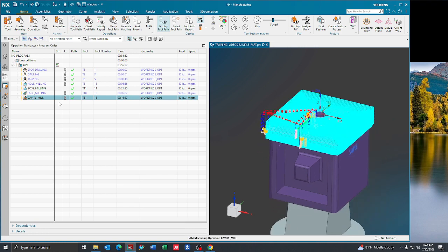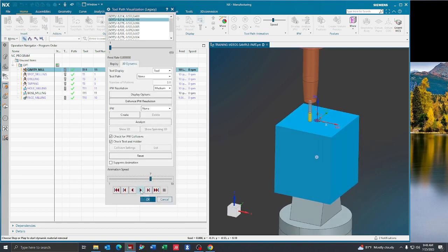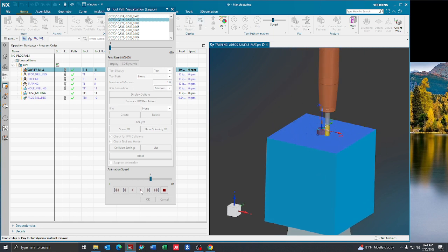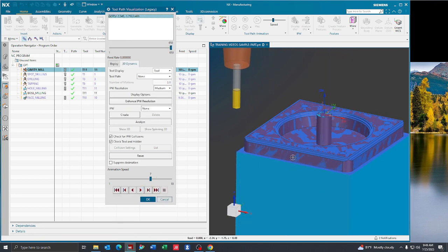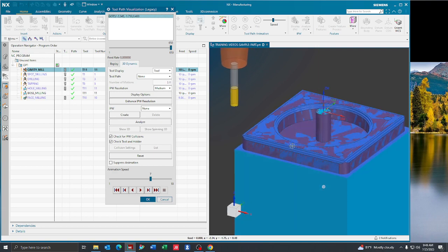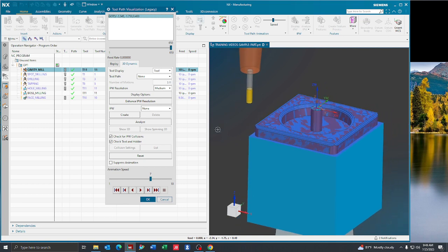So we'll say OK here, and we're going to generate this toolpath. As you can see, it roughed it out. So we'll move this to the top and verify. And then you'll be able to see that we just roughed away all of this material down to that floor level. Now you'll notice that all of these levels where it's blended out and faceted between the blue and the purple, those are all finished material. That's because we don't have any stock to leave on our toolpath.